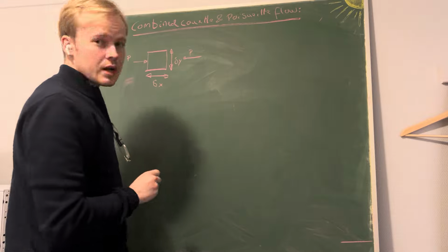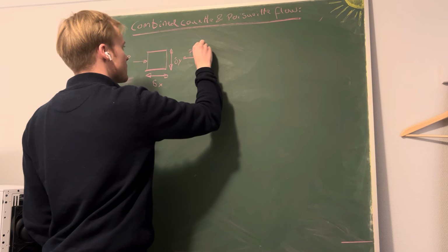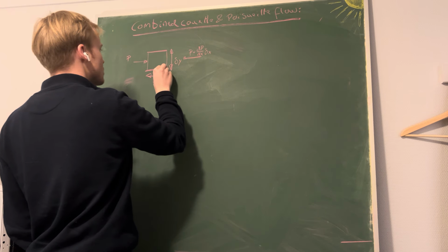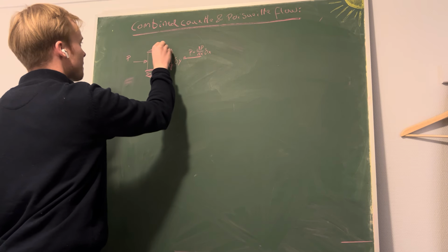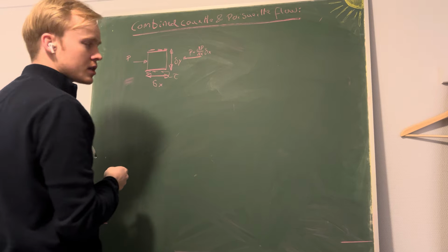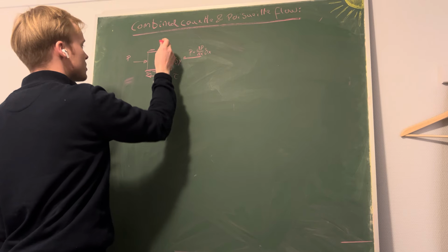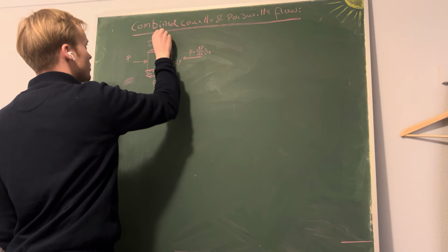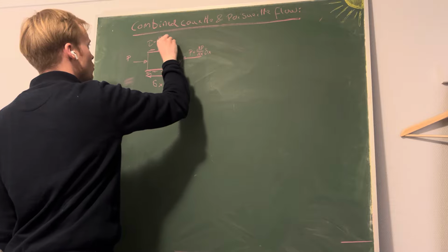I'm going to write up the Taylor expansion for this one just so we can save a bit of time. And then we had shear like this, which was tau, and when we go one step up in the vertical direction, we can approximate this using a Taylor expansion, which becomes tau plus d tau dy delta y.